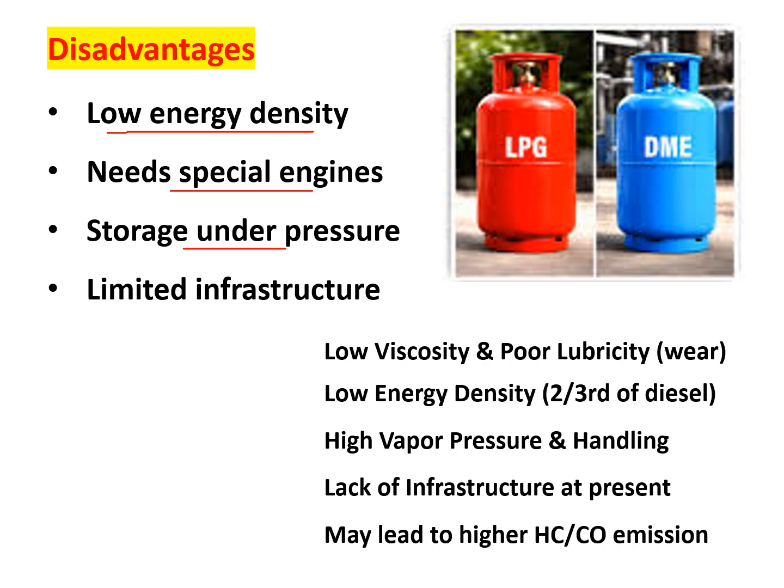Limited infrastructure at present in most countries. The other disadvantages, low viscosity and poor lubricity. That means it will cause faster wear and tear of the engine. Low viscosity and it's not lubricating, so it will cause greater wear and tear.